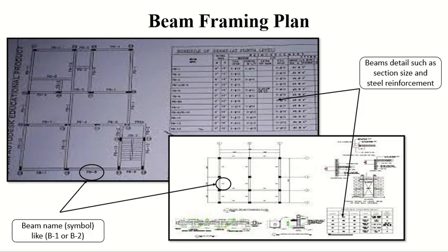It's not here. Okay, but we cut the section, then we make the details drawing. We make the details so that we can see what is happening inside the beam, how the bars are placed and how the stirrups are and so on. But again, some or all of the details are given in the beam schedule as well, and the beam schedule is coded according to the codes which are given to the beams. Similar beams can have the same code.